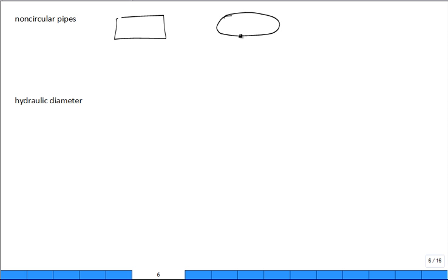The architects like to have that tight space small. Mechanical engineers like to have it large. And the contractor that installs all that stuff likes it even larger. And if you look at the AET, it's huge. You could probably stand up there. All right? But in a lot of commercial buildings, it's very narrow. And so they need to move a lot of air in ducts, and so the height is the restriction. So they typically get rectangular ducts or elliptical ducts. And when they were building that building, the BSE, I saw they had some big sheet metal elliptical ductwork that was being installed.